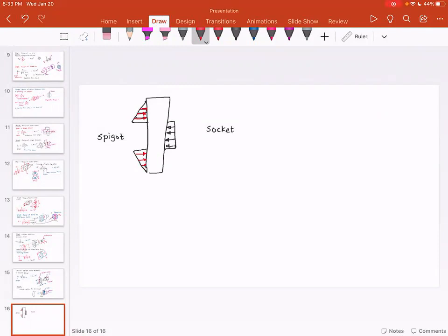And when that happens, you have the spigot, which is coming over here, kind of grabbing the cotter at the center. And because of that, since the cotter has deflected slightly in this orientation, the contact at the end will be minimum compared to the contact at the center. The consequence of that is the loading is the way I have shown over here.